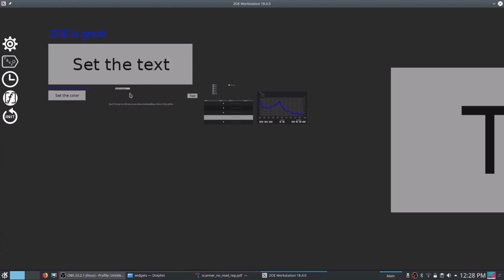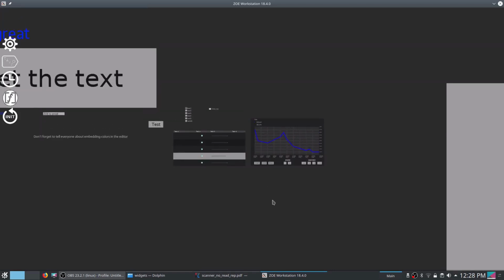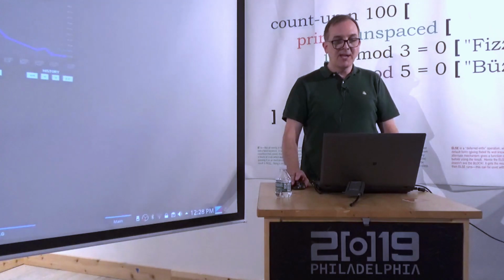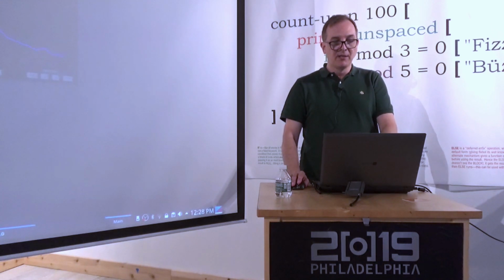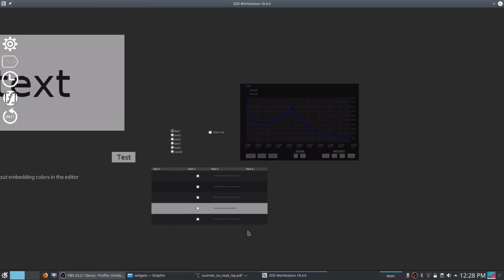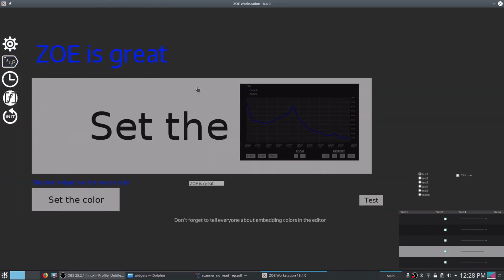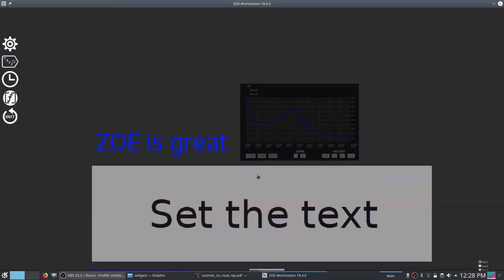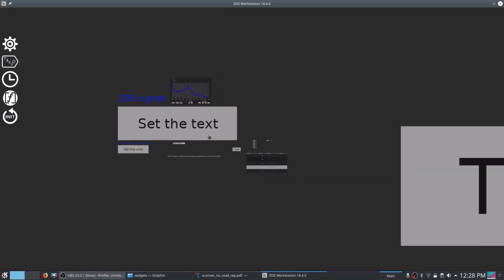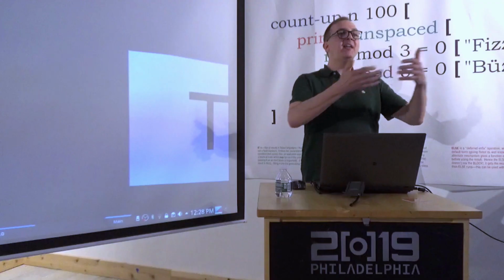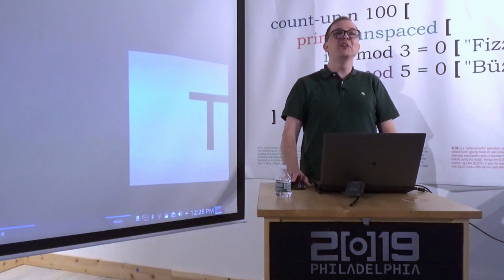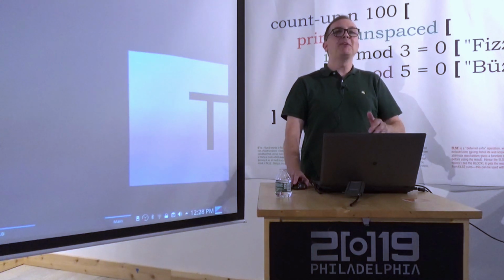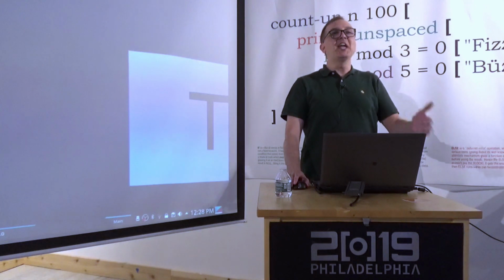So I've laid this stuff down here. How in the world do I move it around? And we use the sticky property again. So basically, I control left click to select, and then I hit P to pick up. So now I've picked this widget up, and notice it's staying with me. So now I just pan and zoom to where I want to go, where I want to place the widget, then I do P to put down, and there we are. You're not dragging a widget somewhere, you're sticking it to your screen, you're panning and zooming, and then you're plopping it back down on the canvas. So that's moving a widget. That's the one thing that people either say that's cool or this is insane.